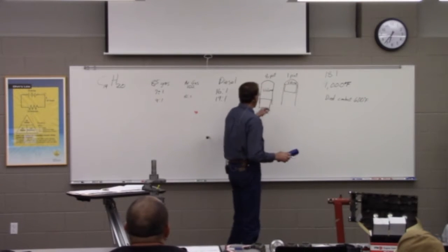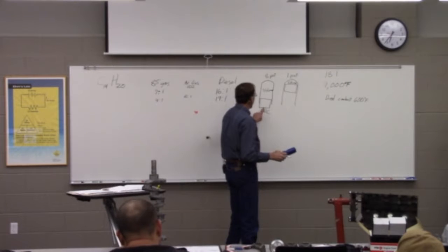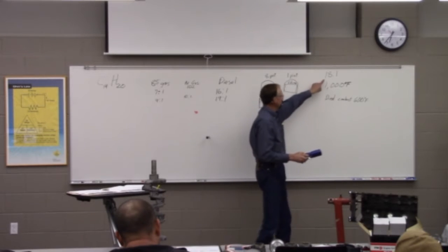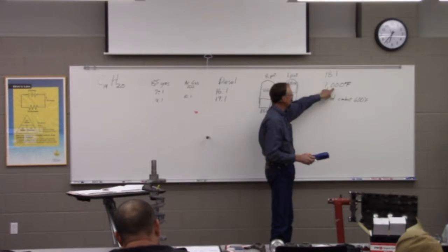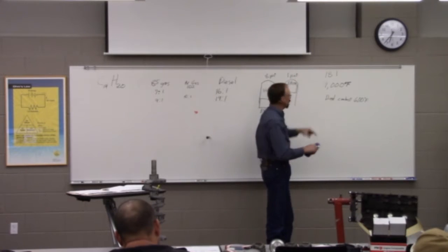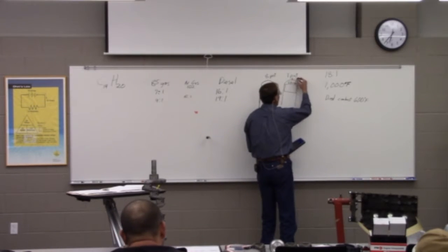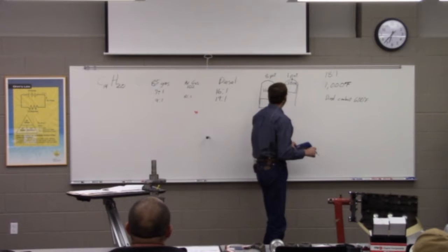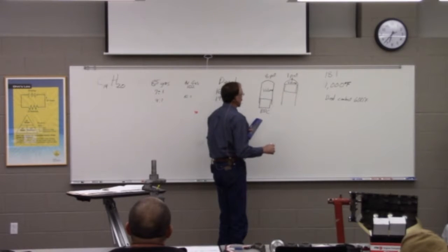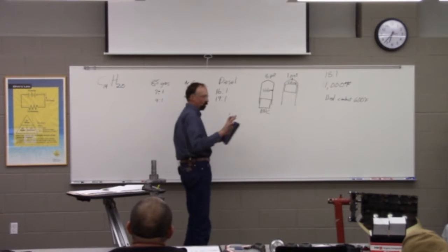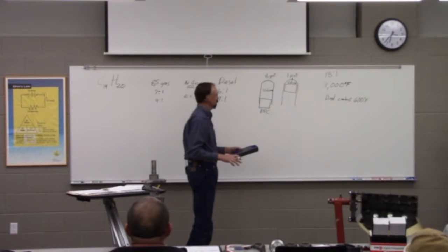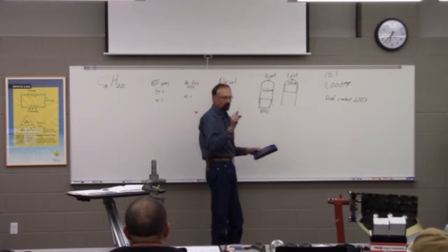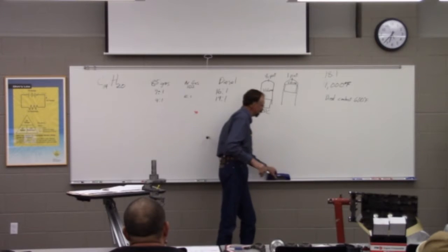So that's why in diesel engines, what's done is we'll run this piston up to here. We've created a lot of pressure and a lot of heat, and then we squirt the fuel in through an injector that's sitting right in here, and it actually combusts as it's coming out the nozzle of the injector. In a gasoline engine, that hydrocarbon works enough differently that we can't do that. It just doesn't work. So instead, we'll have a spark plug here that sparks and creates our ignition source.